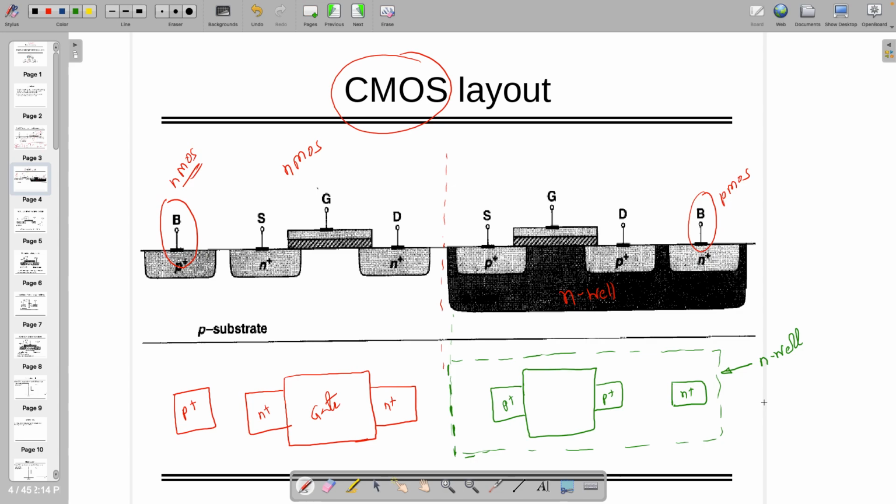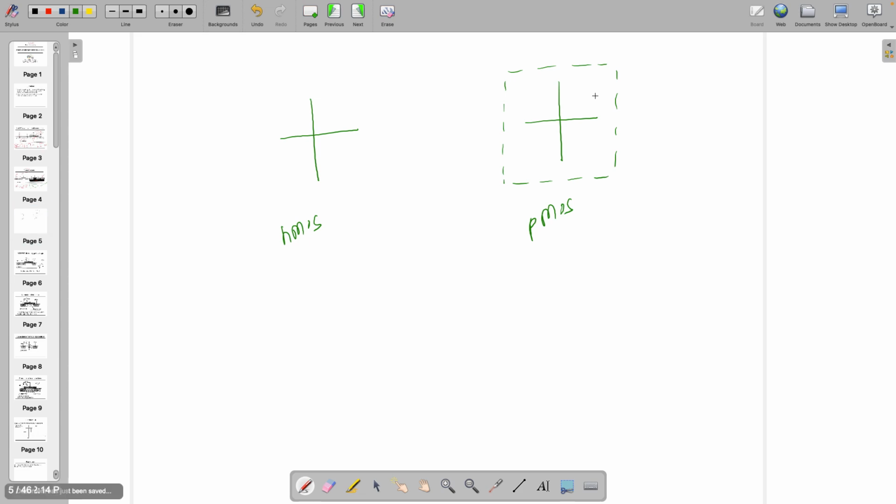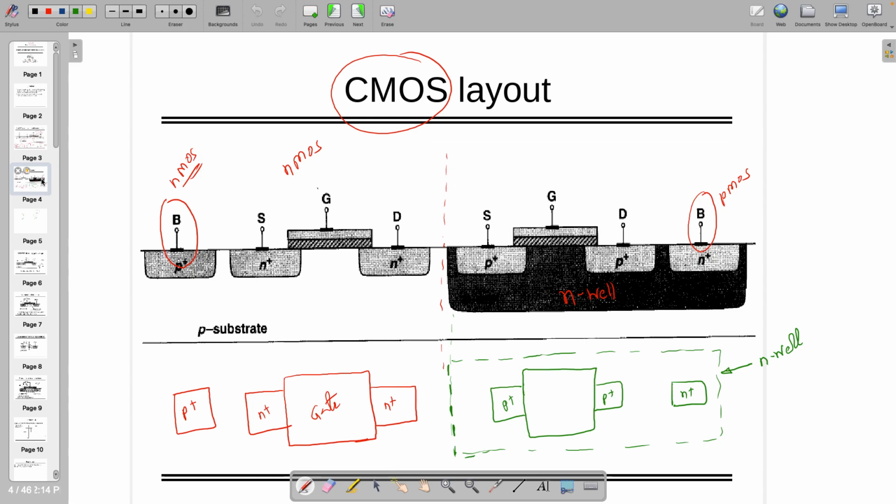If you are studying, let's say, digital MOS where stick diagrams are there, stick diagrams have notations like this. So this indicates it's an NMOS, and this indicates it's a PMOS, right? Depending on what notations you are following, you can draw the stick diagram, and there are certain algorithms using which you can sequence which NMOS has to be first, and you can do the routing, and you can make the required layout. So that is very much useful.